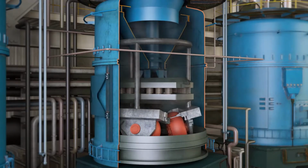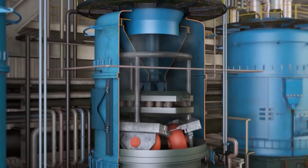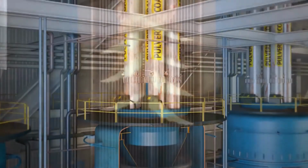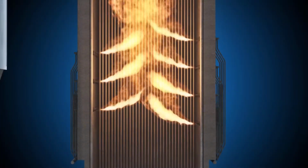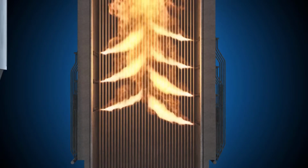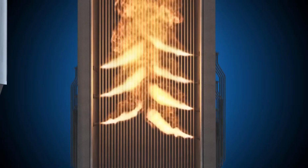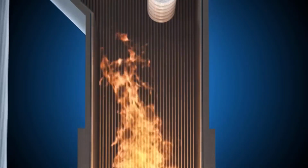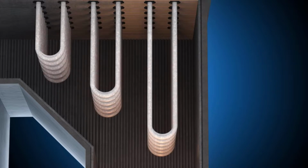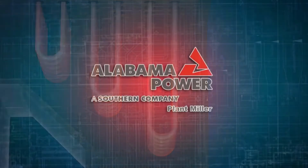Once the coal is a fine powder, it falls off the grinding bowl and is carried by warm primary air, maintained at 140 degrees Fahrenheit inside the pulverizer, to the boiler through 8 burner lines. When the particles of coal reach the burners, they are mixed with secondary air that has been preheated to over 500 degrees to support complete combustion inside the boiler. The combustion of the coal converts its chemical energy into thermal energy, creating a temperature inside the boiler of over 2,200 degrees. That's enough to heat the water in the series of boiler tubes to create steam, which moves onto the turbine to power the next step in our process.